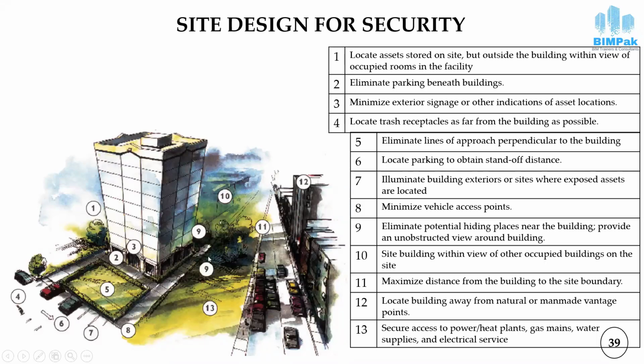The tenth one is to site the building within the view of other occupied buildings on the site. So if there are other buildings, they should be in view of this building, so that if there is security personnel performing their duty in this building, these personnel should have a clear vision of the activities in the near vicinity.